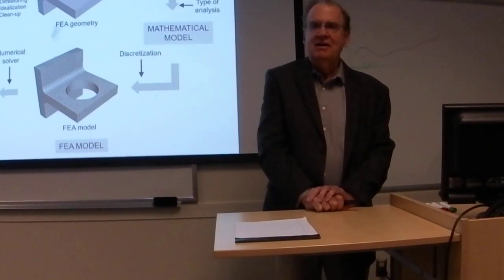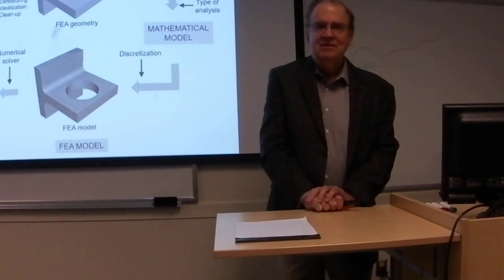So how did ANSYS work? Very similarly, it was the same steps. You upload your geometry, define boundary conditions, generate your mesh, and then run the solver, look at your results, and maybe refine your mesh or your applied loads, and run it through until you have accurate results.